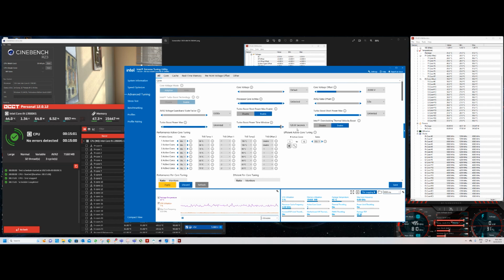There's an option at the very bottom called Core SVID Voltage. That is the name set up in there instead of Core Voltage Offset. So if you don't see this, you have to Google it. But for right now, for Asus, it's Core SVID Voltage, which I'll put in the notes, in the link or information below the video.